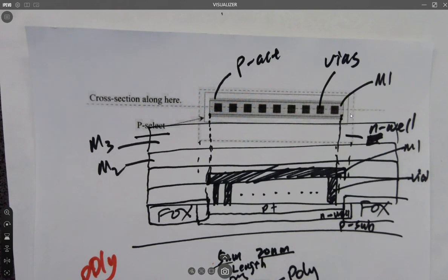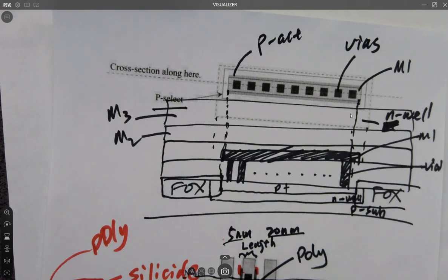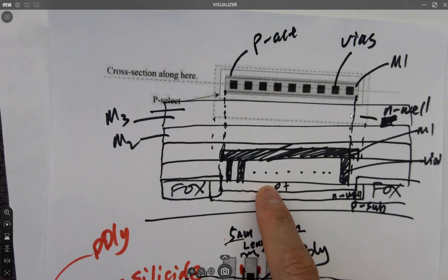In that layer we don't have a poly because it's not a transistor, it's just a wire. So as long as you don't have a transistor, then you don't have the polysilicon at all. You don't need it, that's right. The polysilicon is used as a gate and also used as a cap. So we are forming capacitors using polys as well, but it seems like none of the cases here, right? It's just a diffusion.